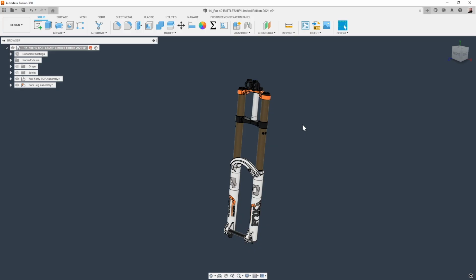With Derive, does it keep the file relatively lightweight in terms of Fusion performance because it's not copying the whole thing in, or can it get kind of bogged down if you do a bunch of this? Yeah, I haven't run into too many limitations, but normally when I'm doing one file, I do notice the performance is a little bit better. Okay, got it. Anything else we should know, or any reasons not to use manufacturing model?